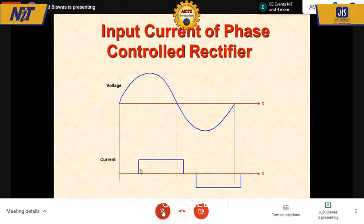In effect, the fundamental current is phase shifted, is made to lag the supply voltage by some angle. Therefore, if the fundamental current is lagging the sinusoidal voltage, there is bound to be some reactive power. So I am creating double problems. First problem was I am injecting harmonics. The second problem is I am creating lagging VAR.